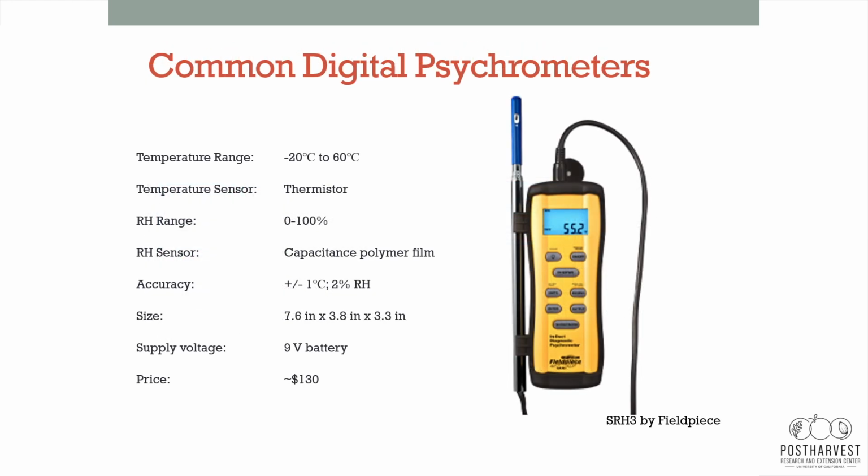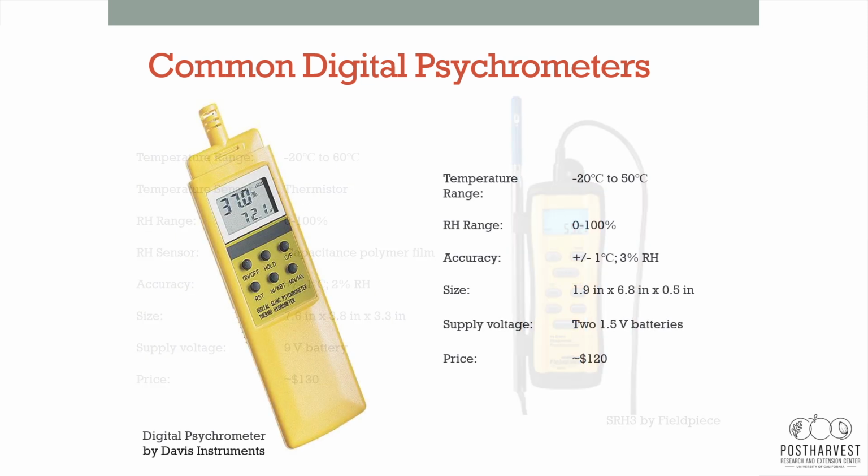We talked a little bit about psychrometry yesterday. There are commercial psychrometers. In other words, this digital interface would offer different outputs, not only relative humidity, but also temperature, dry bulb temperature, wet bulb temperature potentially, dew point, and other additional measurements that allow us to work with psychrometry, or the study of moist air. There are different manufacturers, like the ones that I'm presenting here.